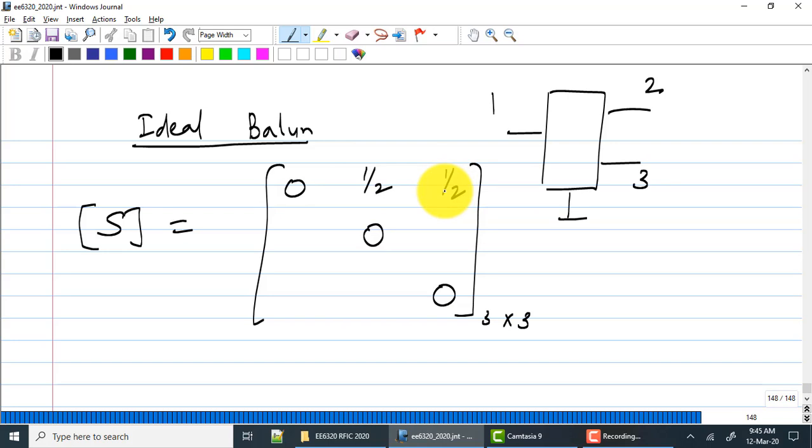But it's very easy to confirm that this is true. Take an N port, given some power P. Through the port you can give a power P. Make sure that when exactly matched, you're getting half the power. You can also define it as the ratio of powers. If you give it in terms of dB, they'll turn out to be exactly the same. The way we have defined it in class is in terms of voltage. Some microwave people do define it in terms of power.